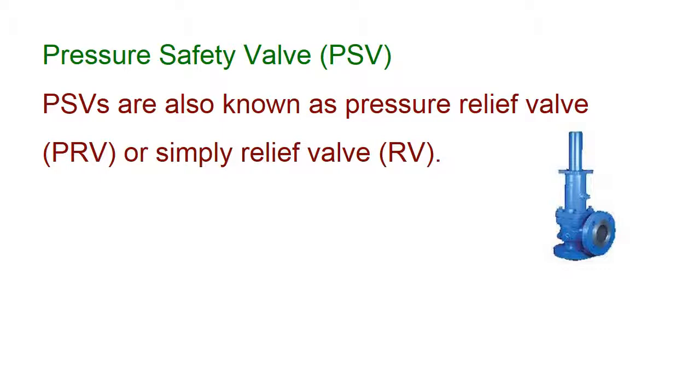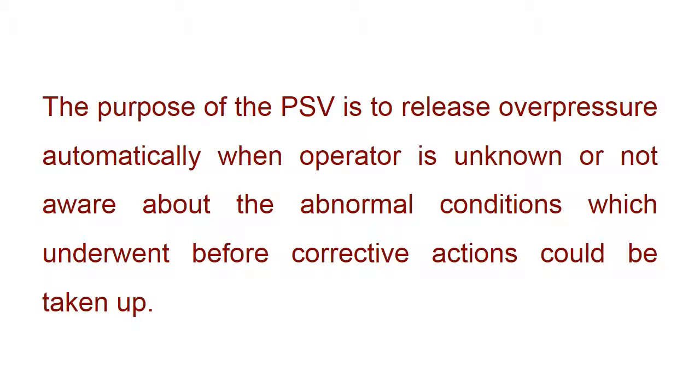Pressure safety valve, PSV. PSVs are also known as pressure relief valve, or simply relief valve. The purpose of the PSV is to release overpressure automatically when the operator is unaware of the abnormal conditions, before corrective actions could be taken.